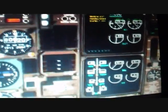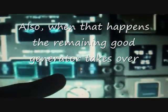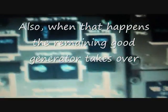Now, when the engine generator fails, you're going to see an indication in amber saying that the right generator has failed, or the left one, whichever one it is, and that click that you just saw. See? Right generator failed. That's the top ICAS warning, or caution, excuse me. Warnings are in red, cautions are in amber. And that click, that means it clicks off. See? Off. Right generator is inoperative.